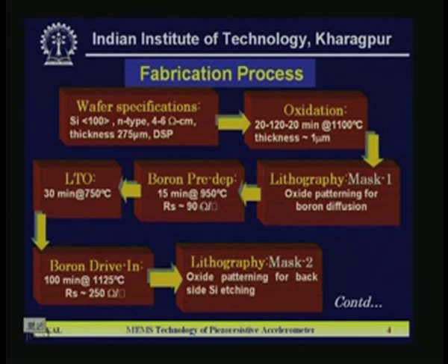With that step, next is LTO. LTO is low temperature oxidation. In particular for boron diffusion, normally in between the pre-deposition diffusion and the drive-in diffusion we follow a step known as LTO, low temperature oxidation. What is the requirement of that particular step?